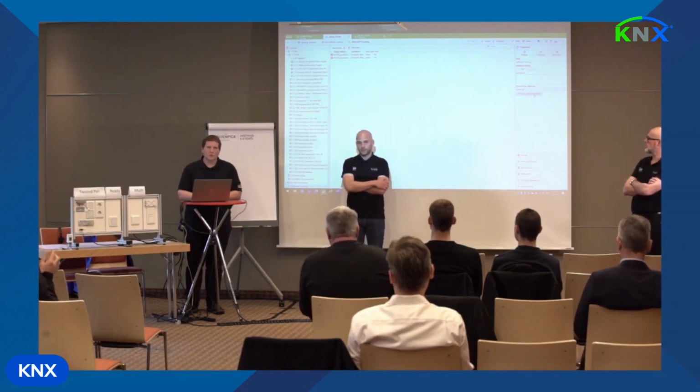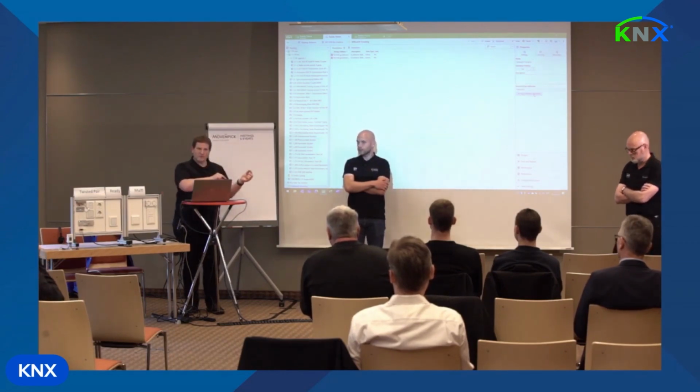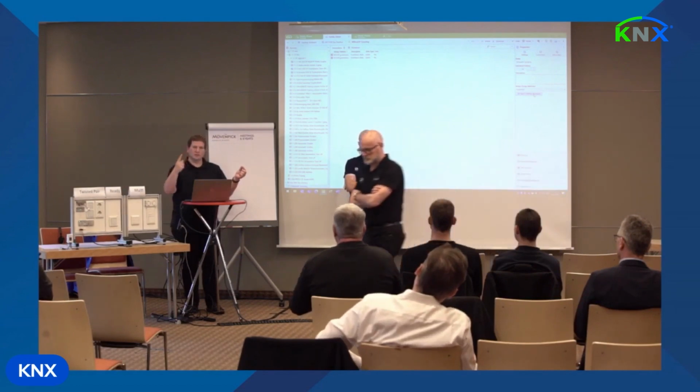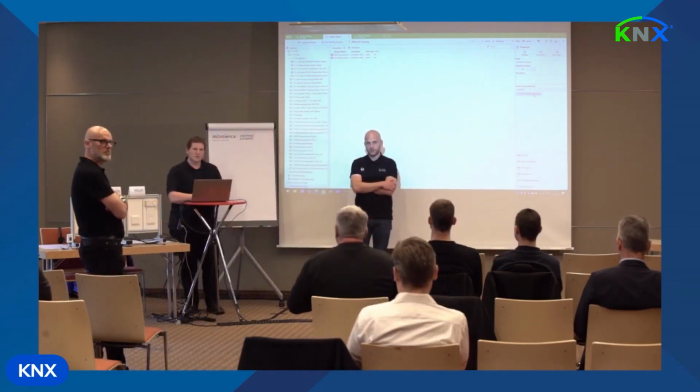Not yet. This is what we're working on, to have something like a middle group in this list, and whenever you add an additional group address to this middle group, it will automatically then be updated here. So to make this more convenient. The reason is that the alternative solution to configure this in the past, and it was a really dirty solution, was manual filter table entries, or having the pass-through couplers flag on the group address.